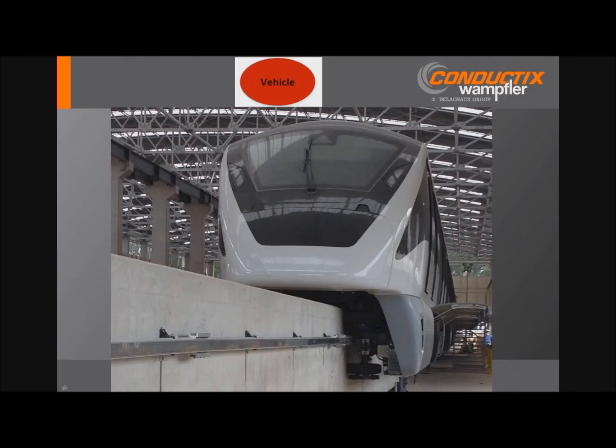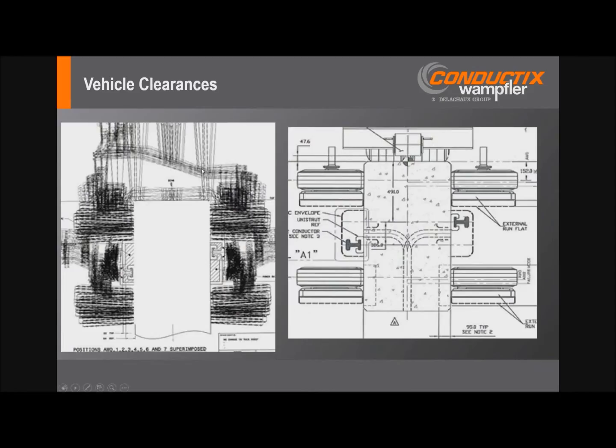Vehicles. Now, under normal conditions, the interaction between the vehicles and the power rails is confined to the collector assemblies. Accurate and detailed analysis really needs to be conducted to ensure that the coordination between the vehicle and the collector movement and the position of the power rail, the guide beam, that contact is maintained. And this needs to be considered over the whole dynamic range of movement of the vehicle in all load conditions.